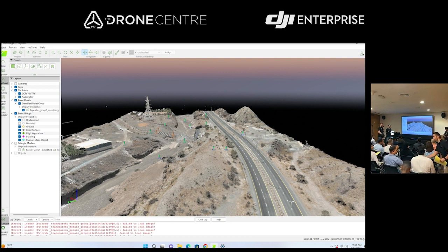Exactly. And an L1 here, if you don't already have a DSM or a DTM, a digital terrain model, if you don't already have that data to input, this is where the L1 may come in quite useful. Do a recce, fly the L1, capture the point cloud reference, input that data to your flight controller on your remote control, and you already have the most accurate data in terms of altitude. So when you use a terrain follow mode, you know that you're using real-time live data. If you're using the L1 for those scenarios for the mountains, create the DTM first and then fly with the P1.